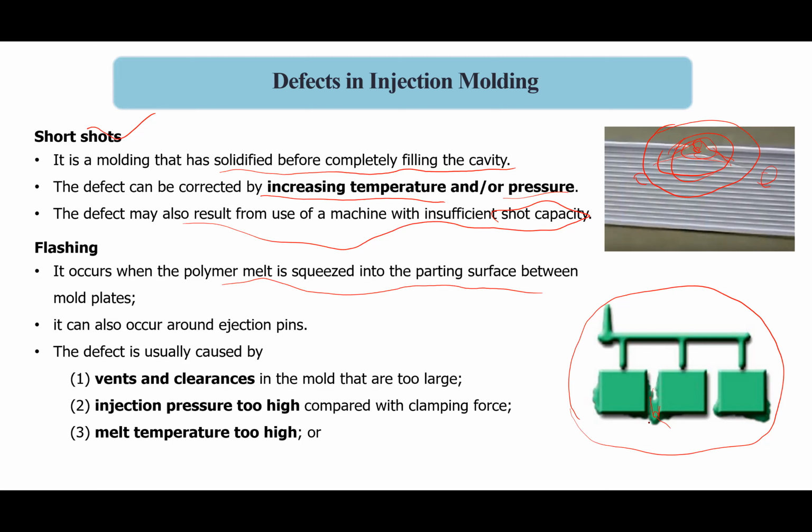Another reason for this is that, the first reason I have told you, the defective mold, and another is the vents and clearances of the mold being too large.